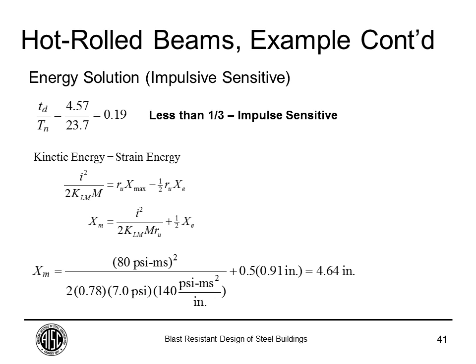Or if your duration is at least 10 times the natural period of your component, you're going to be controlled by pressure. In this case, we are way less than a third, so we're pretty good in the impulsive region. So we can use the equations for impulsive control energy solutions.